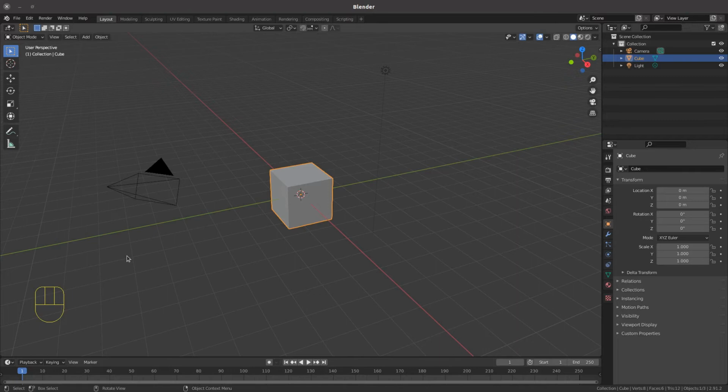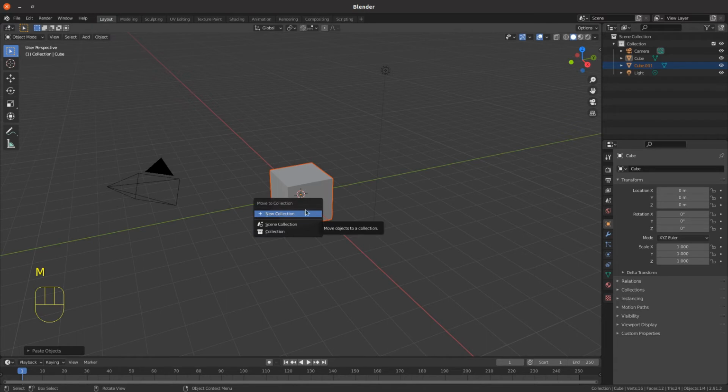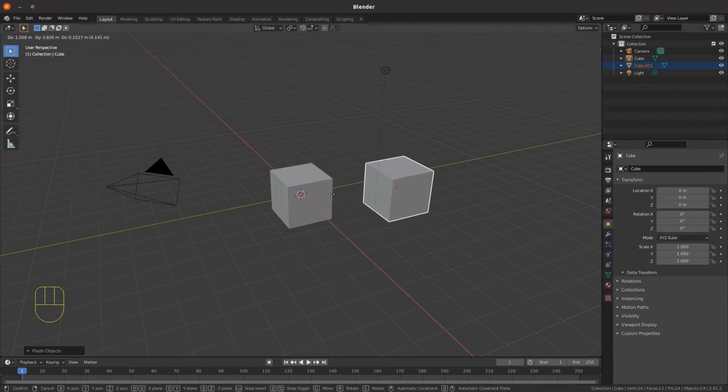The next thing we'll talk about is copying the default cube. You can use the standard across all programs Control C and Control V for copy and paste, and in this, if we go Control C to copy and Control V, you'll see the cube has changed from a yellow selected highlight to a red highlight, which means we've now got a new cube. If you look in the outliner, we've got the original cube, and now we've got a new cube called Cube 001 just sitting on top of the other cube, which means you have to then use another command to be able to move that cube around the screen.